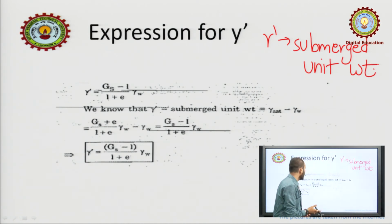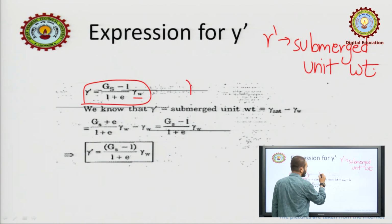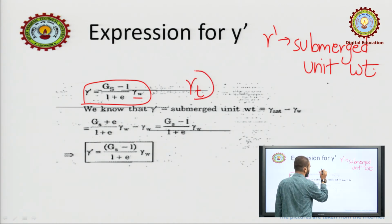What is the relation? (Gs minus 1) upon (1 plus e) into gamma w. Again, this is also obtained nearly from the same equation, the equation for gamma t, with some modifications.